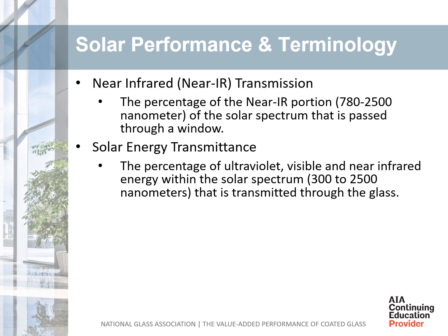The coating design engineer also has the ability to impart changes to infrared transmission, or heat. As noted here, total solar energy transmission is the sum of UV, visible light transmission, and near-infrared wavelengths passing through the coated glass.